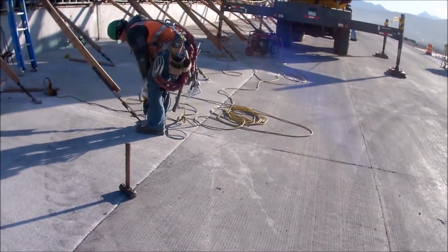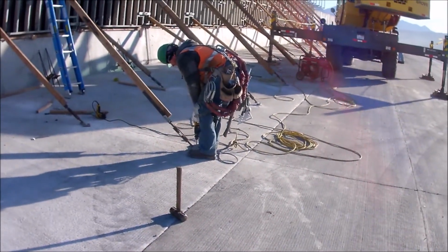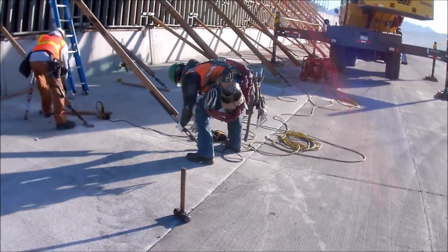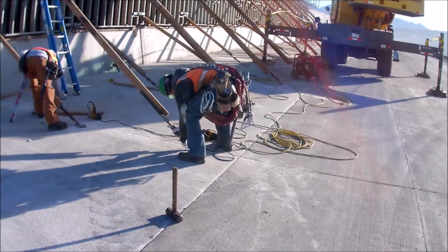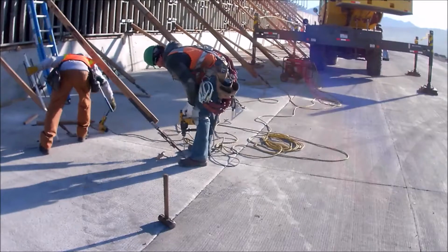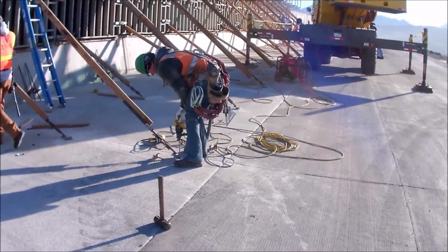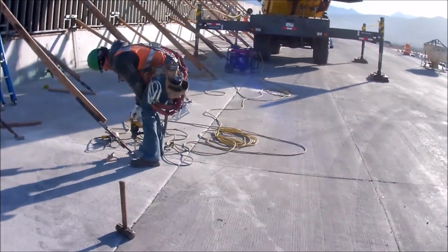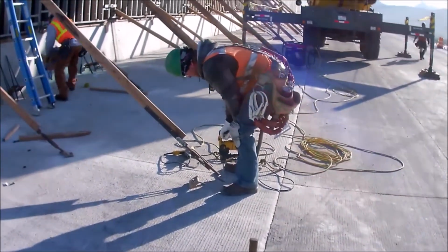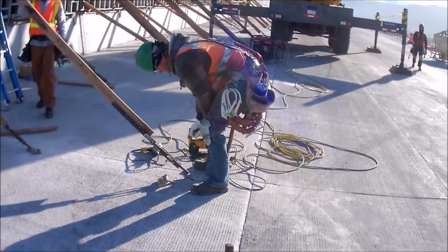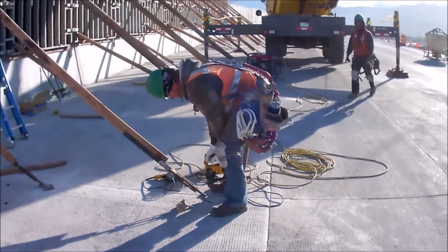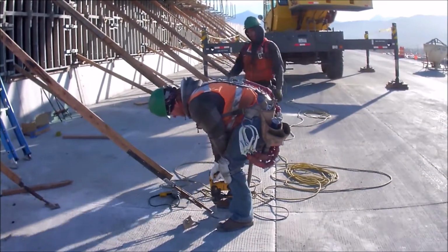Project required PPE includes hard hat, ANSI Class II vest, safety glasses or prescription glasses with side shields, work boots, long pants, shirt with at least a 4-inch sleeve. Certain tasks will require the use of face shields with safety glasses while grinding, chainsawing, blowing out saw joints, and other situations. Hearing protection for noisy areas. Respiratory protection where dust or chemicals require it.